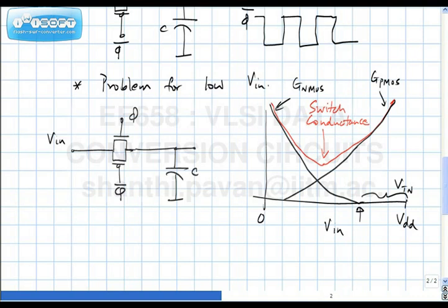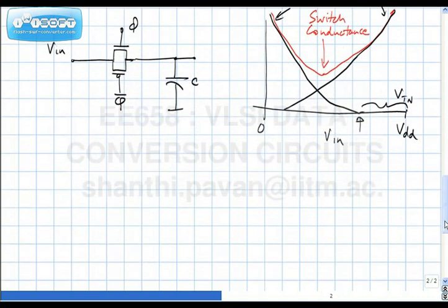So even though you probably mitigated to some degree the distortion that could occur when the input changes, you should definitely expect to still see harmonic distortion when the input changes, simply because the resistance of the switch is being modulated by the input. So this is a vague attempt at making things work reasonably okay.